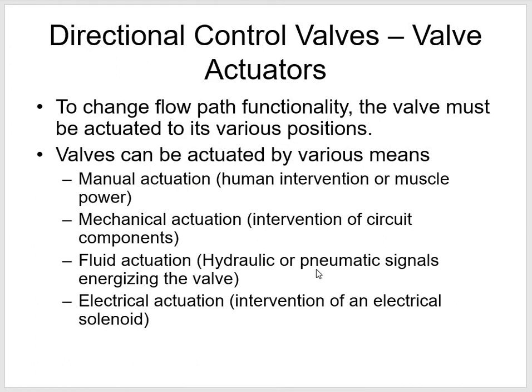Fluid actuated, of course with hydraulics it's oil, with pneumatics it's air. You can actually shift that. That's usually referred to as pilot. Pressure is used to shift it, and then of course it can have electricity used to shift it, and that's using an electric solenoid to shift the spool.